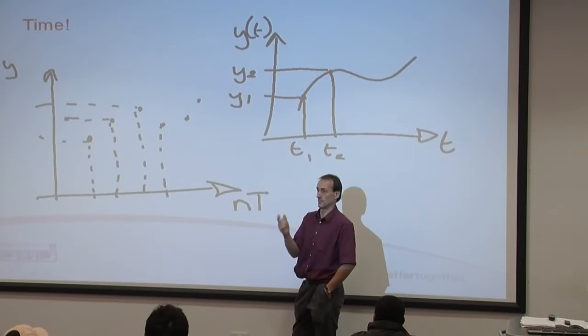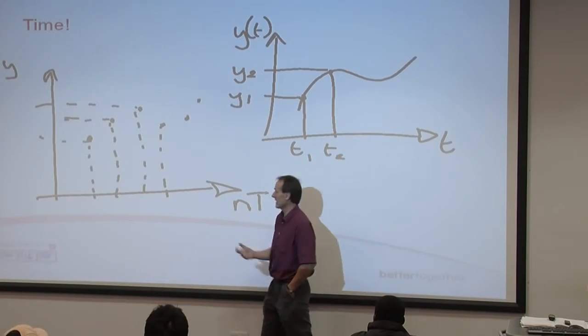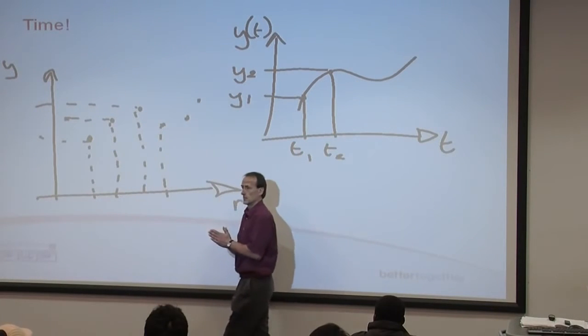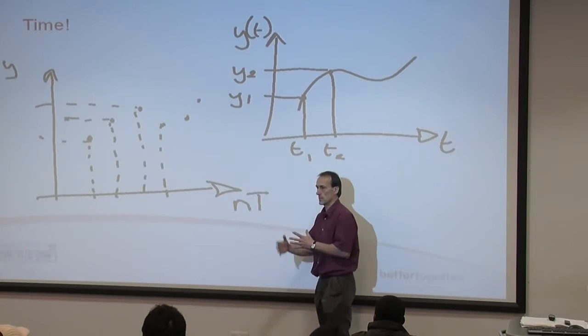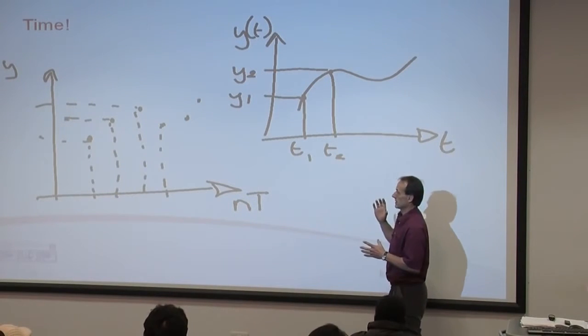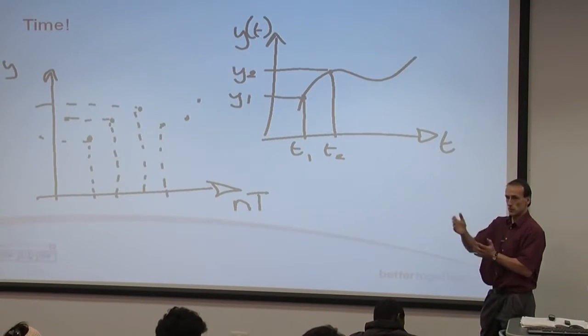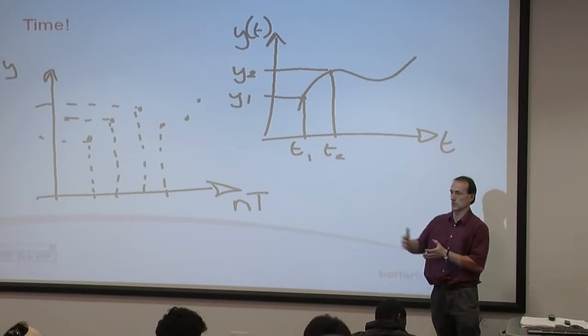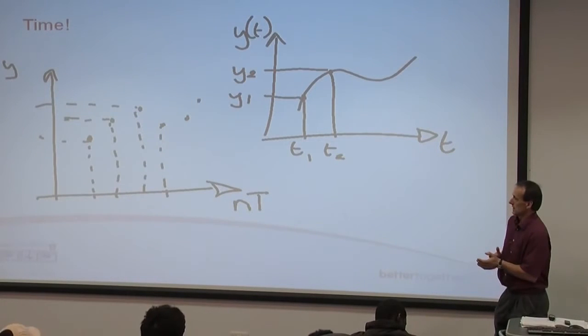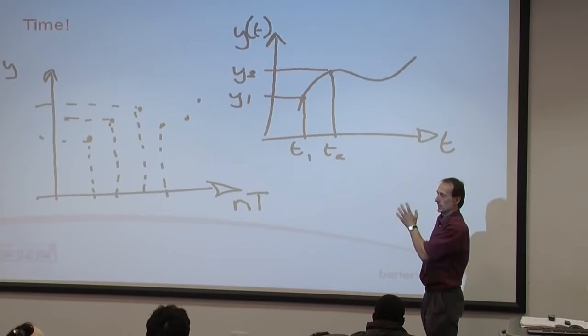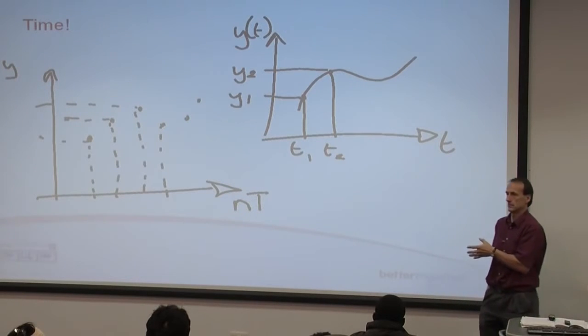No. Why not? Yeah, I cannot make delta time approach 0 because it's restricted by the fact I'm now operating in a sampled data environment rather than what you and I live in, which is a continuous time environment. So strictly speaking, we can't do differentiation on that system.